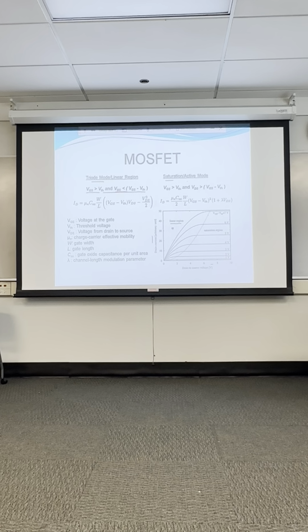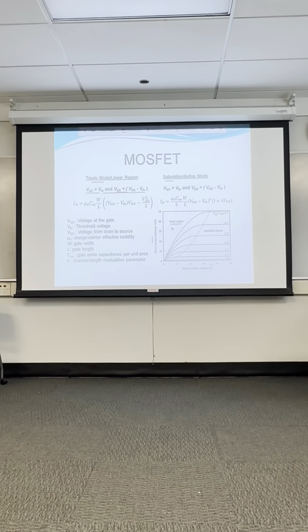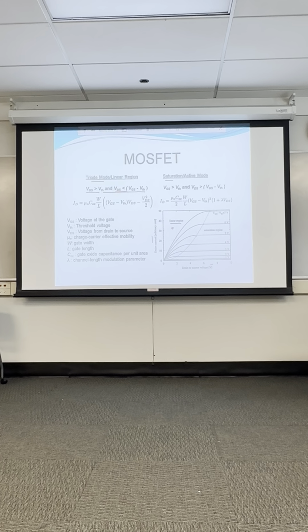If the MOSFET is in saturation, what we came across was that if the gate to source voltage or the drain to source voltage is increased too high, the MOSFET begins to saturate, which means that the drain current flattens out right here, and as the drain to source voltage keeps increasing, it stays in saturation, so it gets a fixed output.